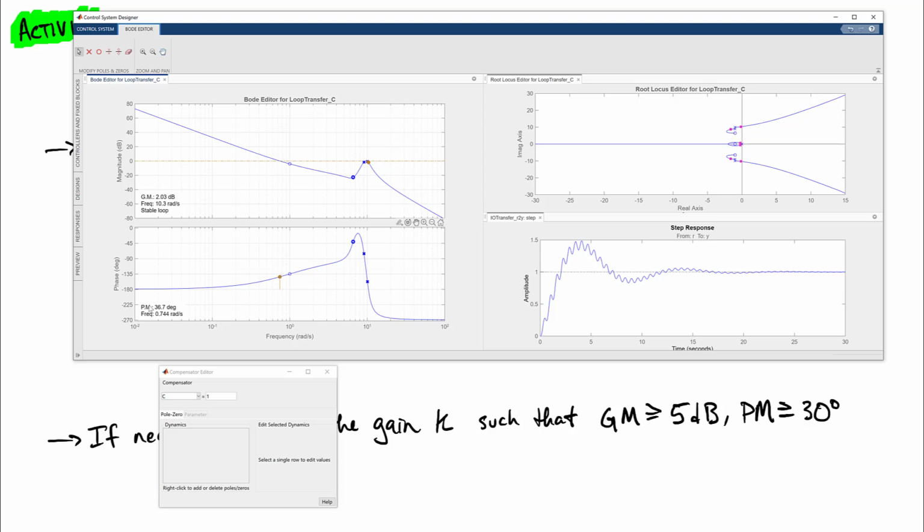So whenever we're looking at multiple phase margins or multiple gain margins, we're always looking at the smallest one, the smallest absolute value, in order to quantify the one that we'll use for our actual phase margin. So that's why we're selecting this one, which happens here, rather than the 2 that happen over here.